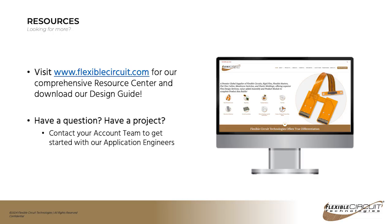FCT doesn't have standard panel sizes. We have some tricks we use to optimize the panel size based on the size of the circuit. The problem with using just straight standard panel sizes is a lot of times you'll have circuits that just don't fit on any of your standard panel sizes. And so what happens is you waste a lot of material. So by being able to modify the length of our panels, we can basically just make our panel size fit the circuit layout and optimize the material usage. So I think that answers the question.